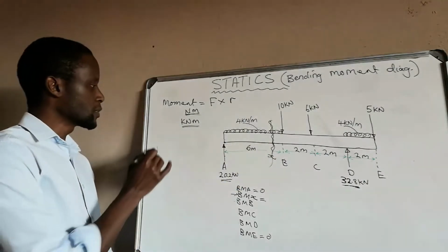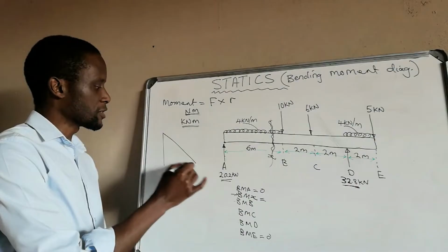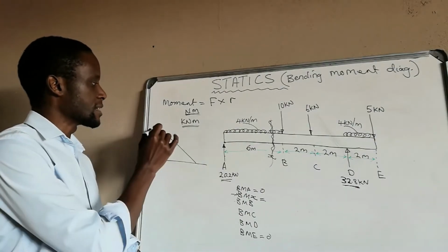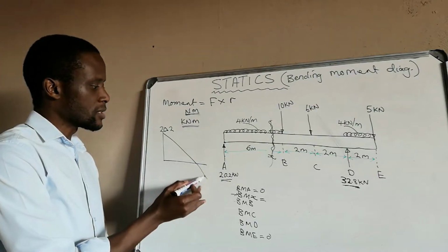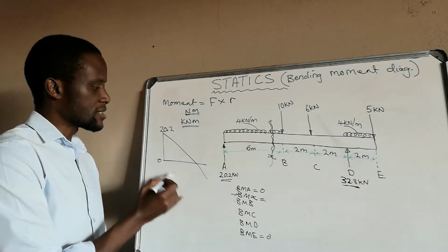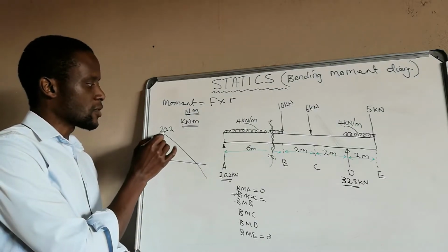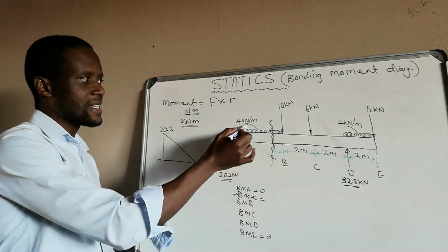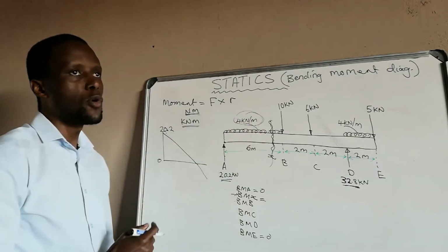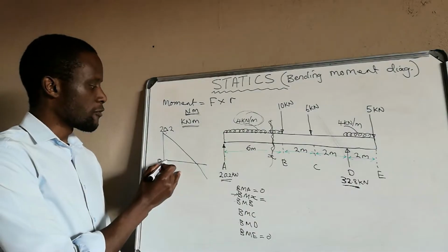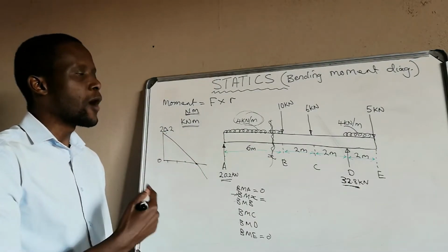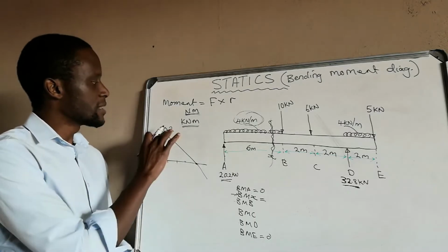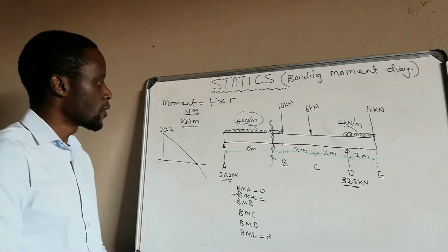So what we will say is that from our shear force diagram, this is what we have seen, is that we were at 20,2 and we brought down this 20,2 until it reached our 0. What brought this 20,2 to 0 is that uniformly distributed load of 4 kilonewtons per meter, until it reached 0. How many 4 kilonewtons per meter are in the 20,2?